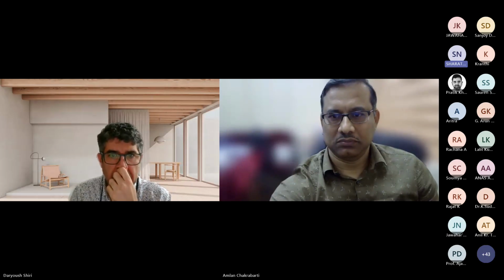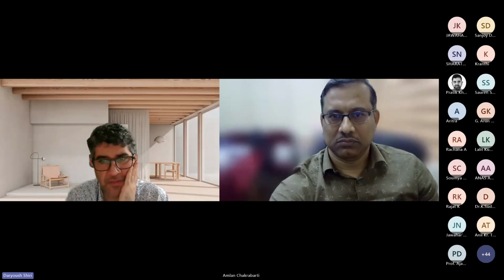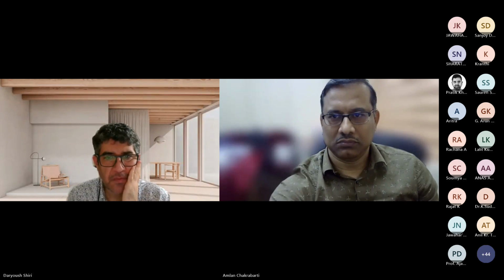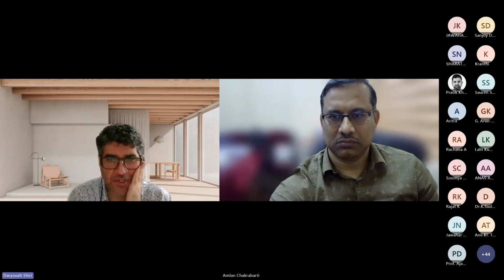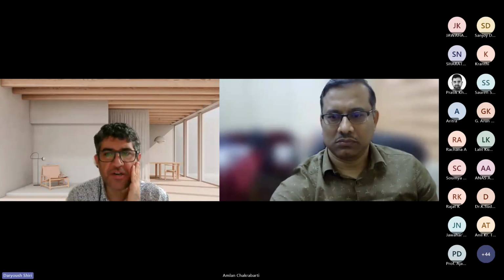Dariush, I think there is a question on how to implement via bonds in the layout, especially for the CPW and the charge lines. I think you addressed this in the presentation, but if you want to take this question up. Yeah, we have default air bridge. We have air bridge by default in the layout generation.